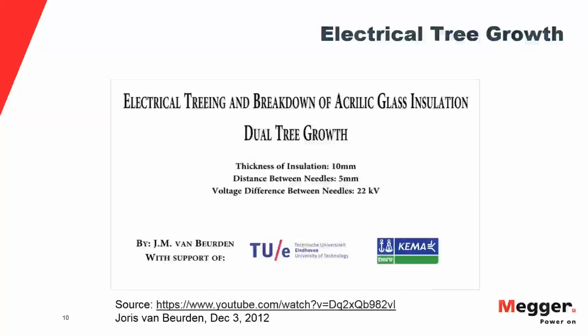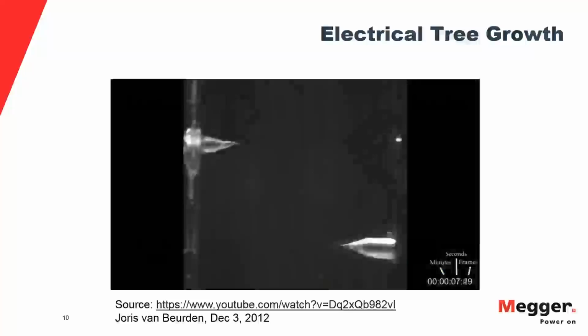and they're all experiencing partial discharge. And finally, in the top right, we have an example of a misaligned splice where you can see that the crimp body of the splice was outside of the black Faraday cage of the splice body, and that caused, of course, partial discharge. And as you see in the picture here, that's how the splice was found, with that crimp outside of the middle of the splice.